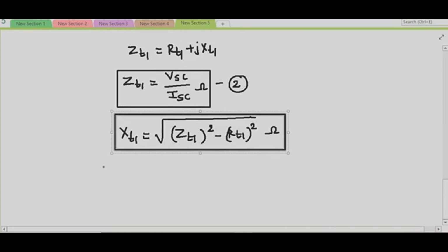Right? It is very important, students, here to note that when the primary is short circuited and the supply is given to the secondary, all the data will also belong to the secondary side in that case. Then the constants of your equivalent circuit calculated from this data will be obviously referred to the secondary side only, right?